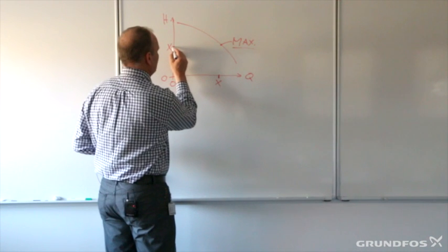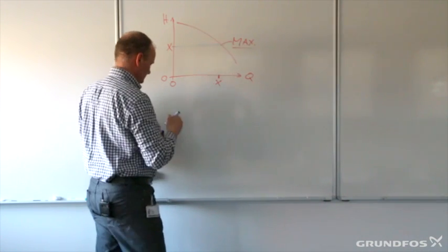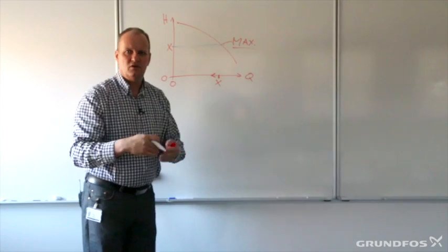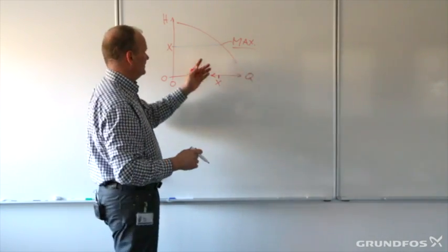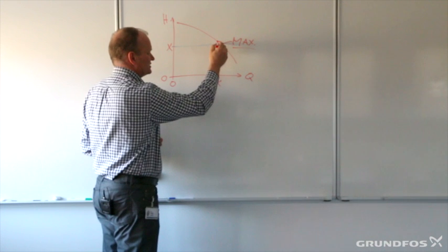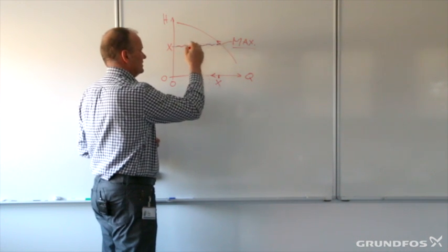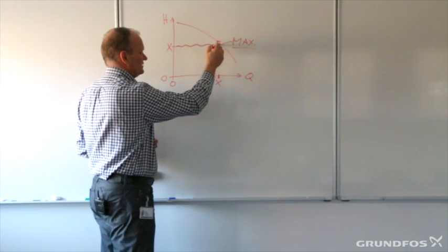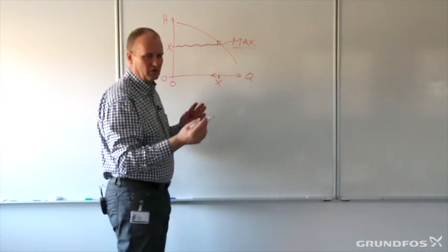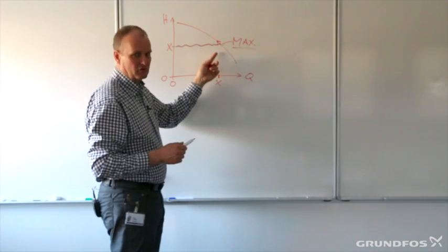And what that means is that as the load is going down, the need for flow is going down because these already mentioned valves are closing. Then instead of starting to increase the pressure, the pump will adjust its maximum curve according to this, at all times securing that the duty point will be on this line here. And the duty point, remember, is the cooperation or the cross point between pump curve and control curve here.